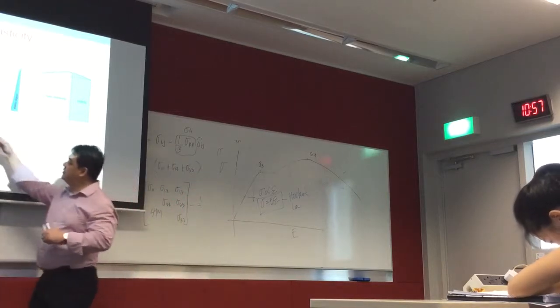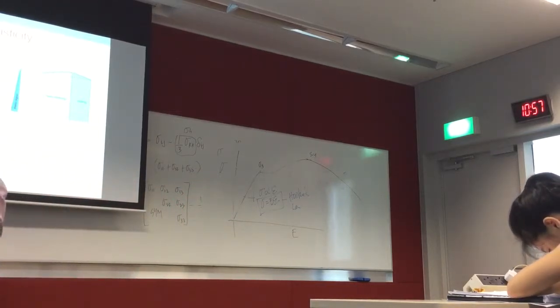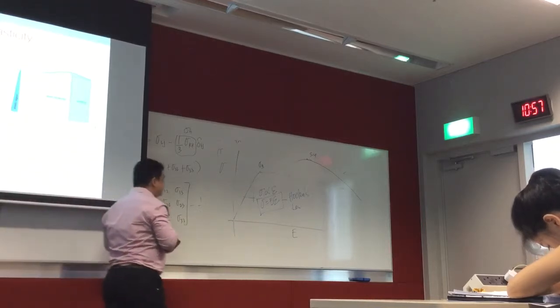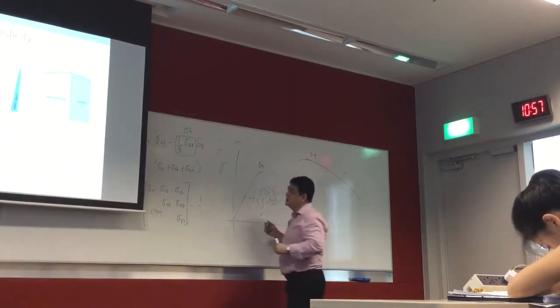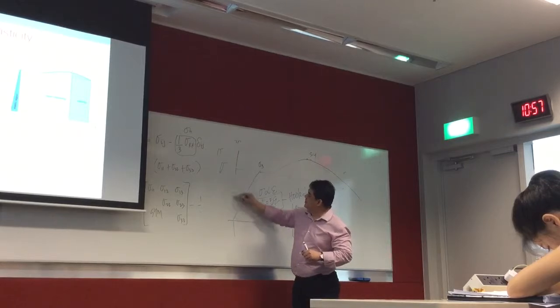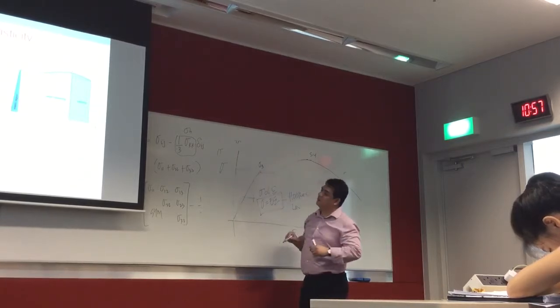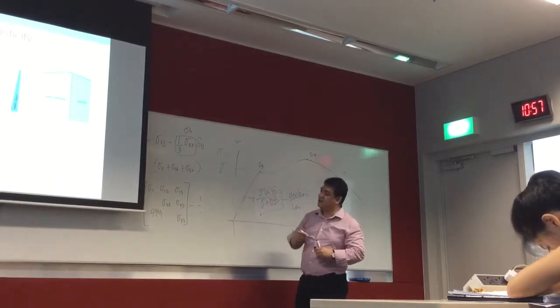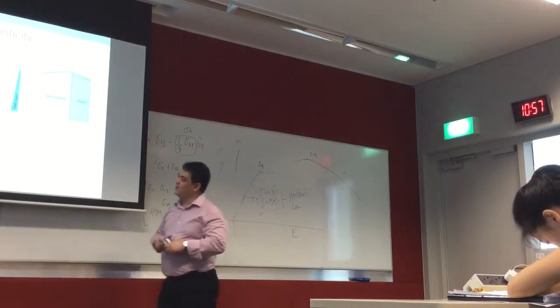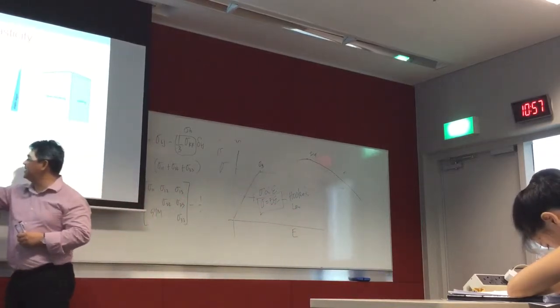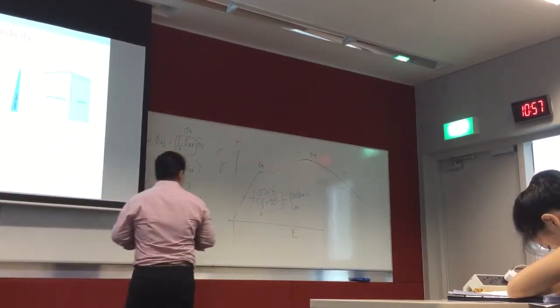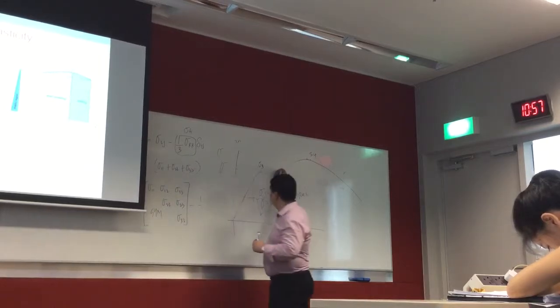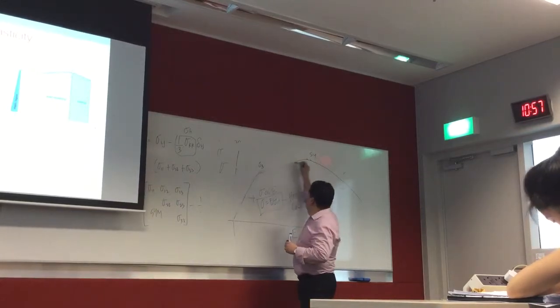This one here has to do with rigid linear work hardening. Again, it's not perfect. And then finally, you have probably the best one, elastic linear work hardening, which predicts your stress strain curve to be like that.